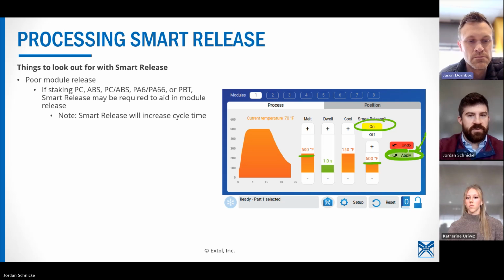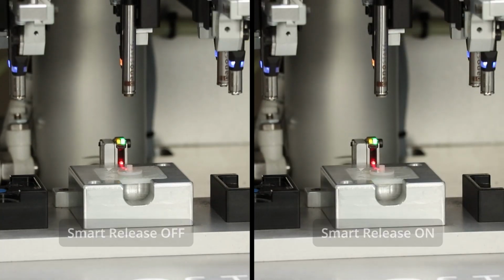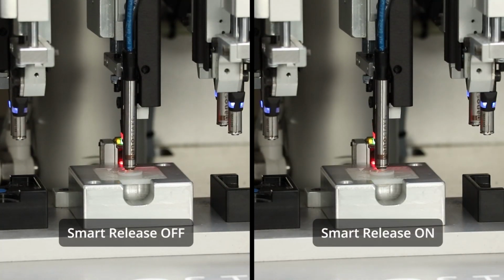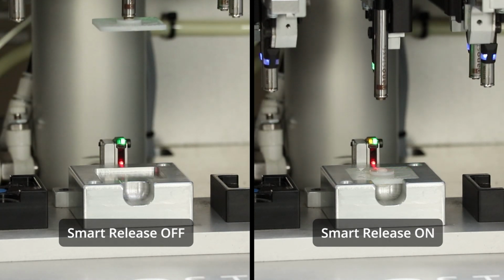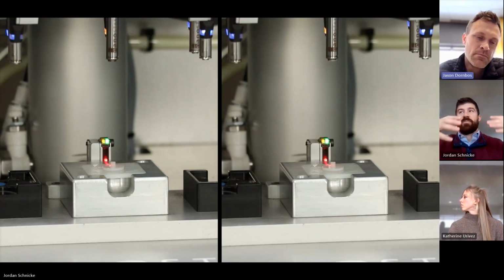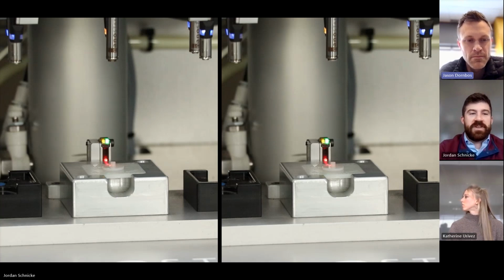If it loads. Sorry, guys. All right, so smart release off on the left side, smart release on the right. You'll notice that it's going to take a couple more seconds on the right side once these modules reach position, but the module retracts, whereas without, it pulled the entire part out. There's no clamping tools or anything on this, so it'll pick up the whole thing. This can damage the modules. This will obviously not have great results for your part and create some headaches where you start to get plastic building up on your equipment.